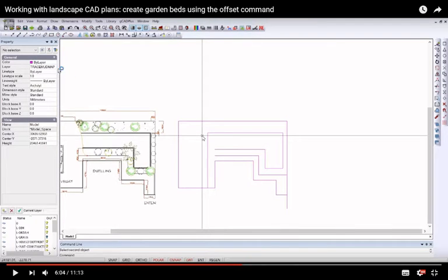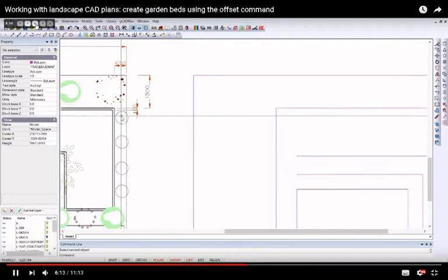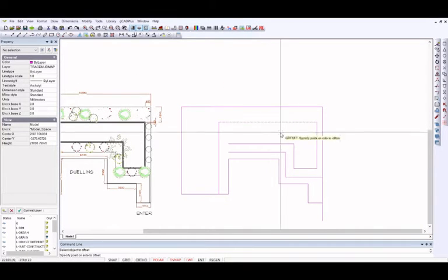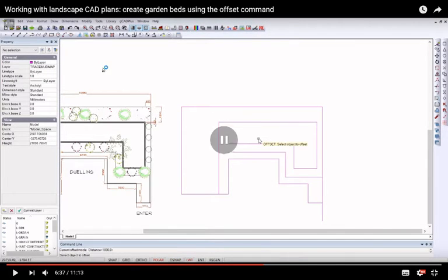I probably wouldn't be going past 2 times, but just for a bit of fun, we'll speed it right up. Our shape nicely defined. It does have to be edged in width with a 100 mm offset, so again we can repeat the offset command, pick the object to offset, and this will be key as we work around picking all of the lines. Far better to gather all those lines up, join them together now as a polyline, and then offset. So you can still kind of understand it at 3 times, or 200% faster, but yeah, I think about 70% is probably the max, and then 40% is kind of comfortable, and it's going to save you a bit of time.